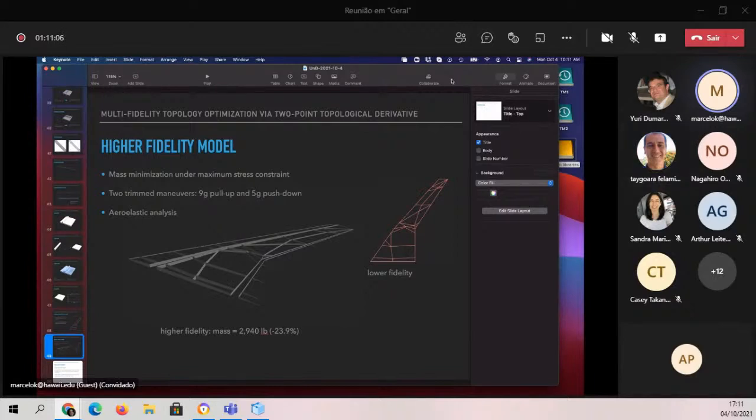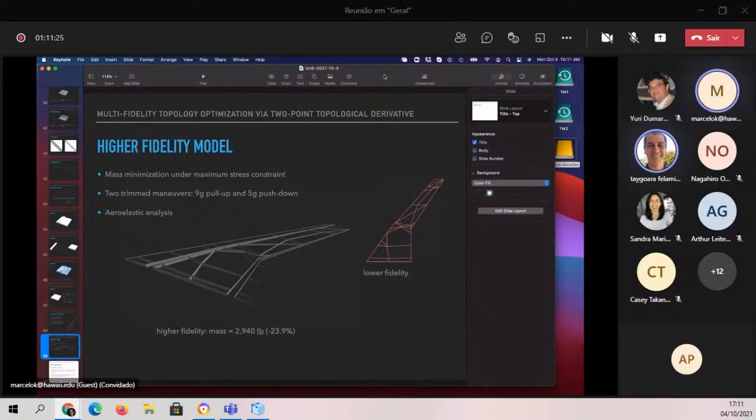Yes. This is algebraic and keeps a really good quality of the mesh. Because we have several methods where you must solve a PDE problem. Exactly. To find the new mesh. And we just want something faster. Exactly. The Winslow method is a non-linear equation to solve, right? Yes. And it's very sensitive to the initial conditions and all of the stuff. And so, absolutely.